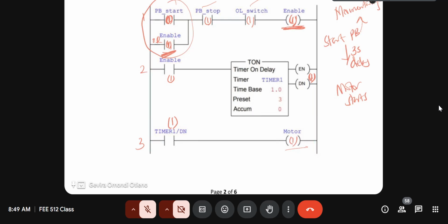We want to press the start button, hold that press for 3 seconds, then the motor starts, because then it shows your intention of starting the motor. It's a security mechanism, because somebody might by mistake nudge or just touch the button, and then the motor starts when they never intended. But when you long press, when you hold the press for 3 seconds, it shows that your intention is really to start the motor.